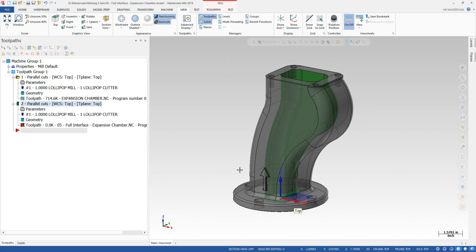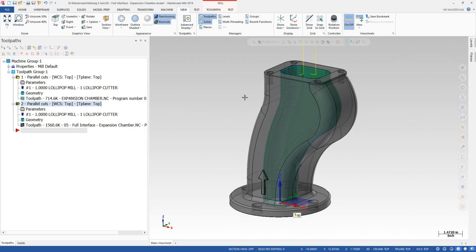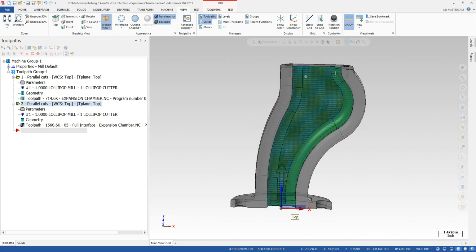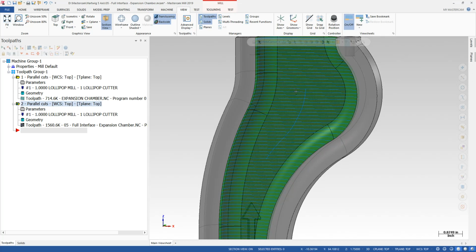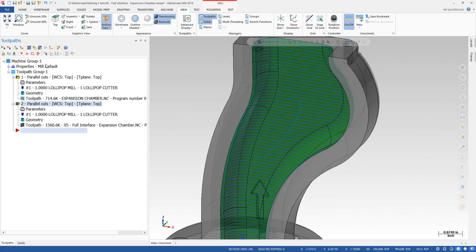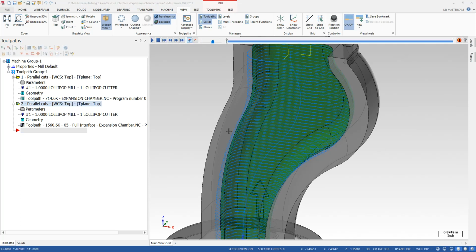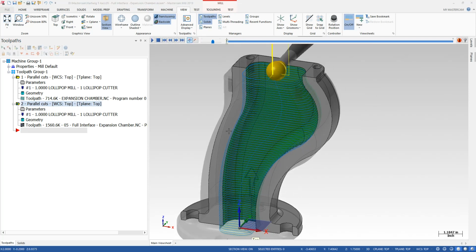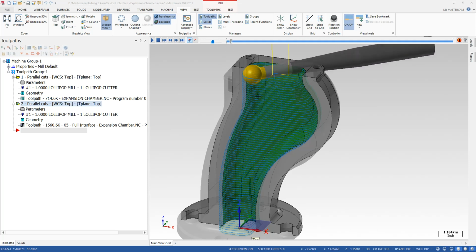It takes a few seconds to generate this toolpath. Pretty quick. Toolpath looks really good. Look at my section view again. Toolpath looks really good, really clean. Motion comes back out of the part. Fairly nice. And if I backplot this toolpath, and I live by backplot because it's quick and fast, there's my tool going all the way around. And all of you think, what is he doing?